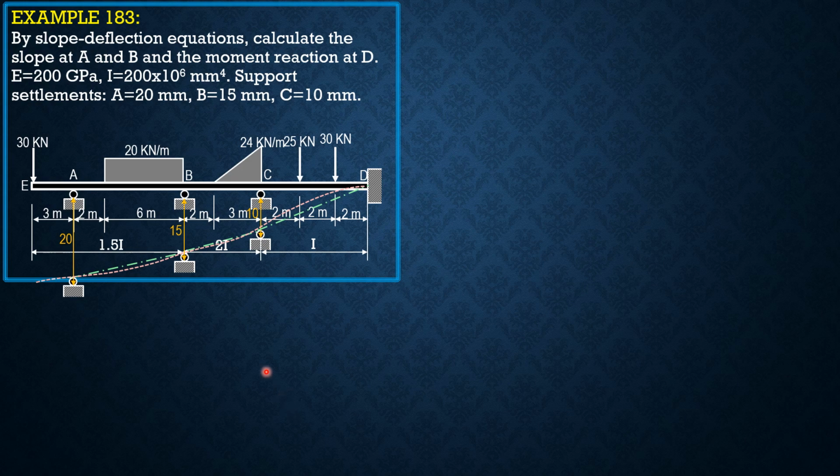So moment at A, moment AB is negative 30 times 3. So it is negative 90 kilonewton meter. That's the overhang. So we set up moment equation for AB and BA because both ends have moments. And for the fixed moments, we have to consider strips.